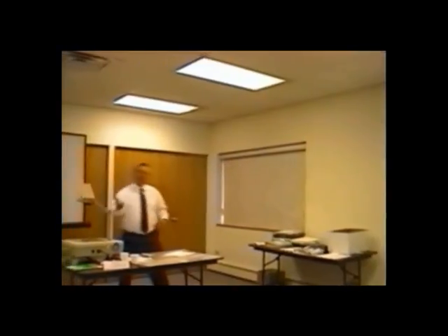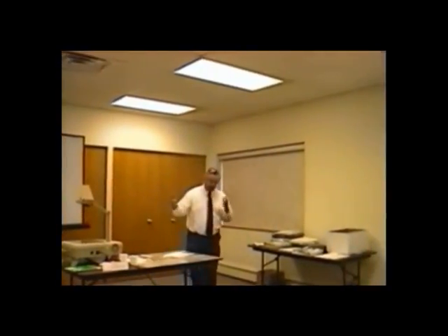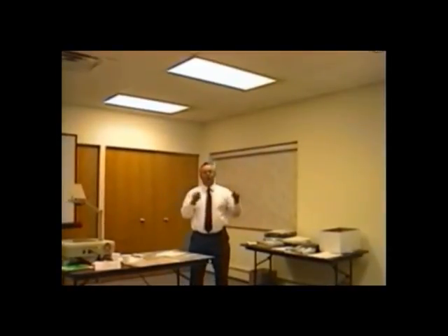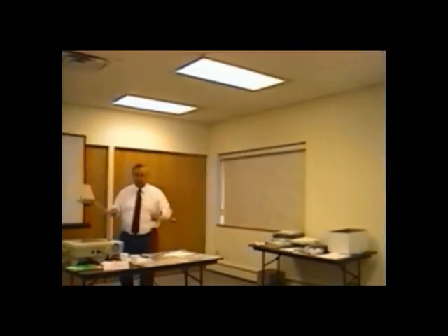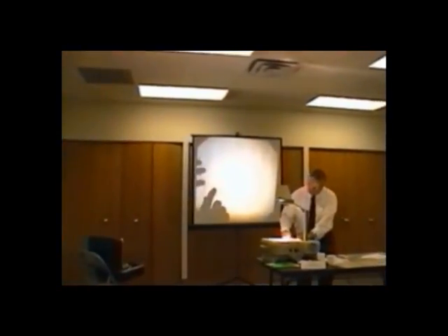All right, so, I'm sorry, so let's go back to the cold suction line. So when we do charge a system to beer can cold, I have to tell you that those systems are absolutely overcharged, and typically beer can cold is 2 pounds overcharged. 16 ounces equaling 1 pound, okay? Now you know why we have compressors that fail. Let's go back to the other methods. We talk about technicians who say, I'll put my amp probe on there and we'll just charge it to the RLA, the running load amps, and I'll charge it to the compressor amperage.